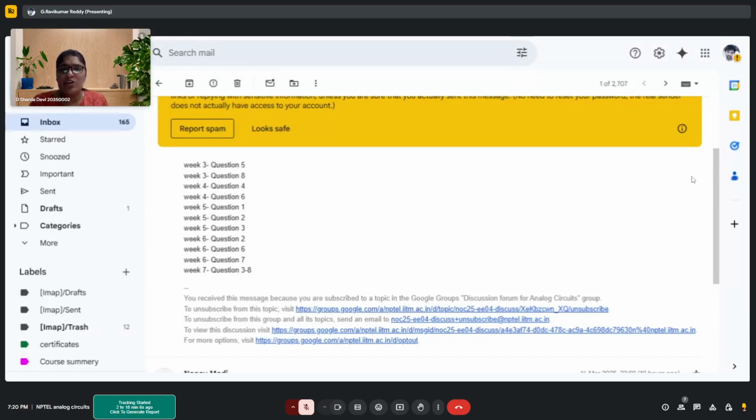From the phase, we can understand that a 180 degrees phase shift is there. Yes, but we have to see the magnitude criteria along with the phase shift, right, ma'am? If the condition A beta should be less than 1, then only it acts as an amplifier, right, madam? Oh, okay. So you're saying, what if the Barkhausen criteria is satisfied and it moves to an oscillating phase? Yeah.